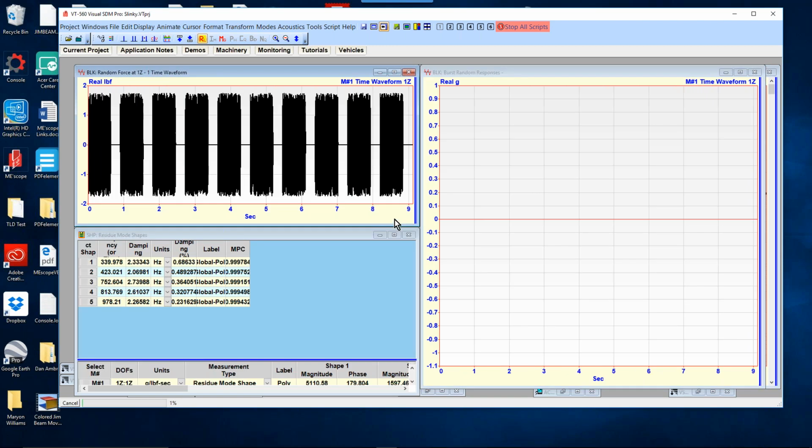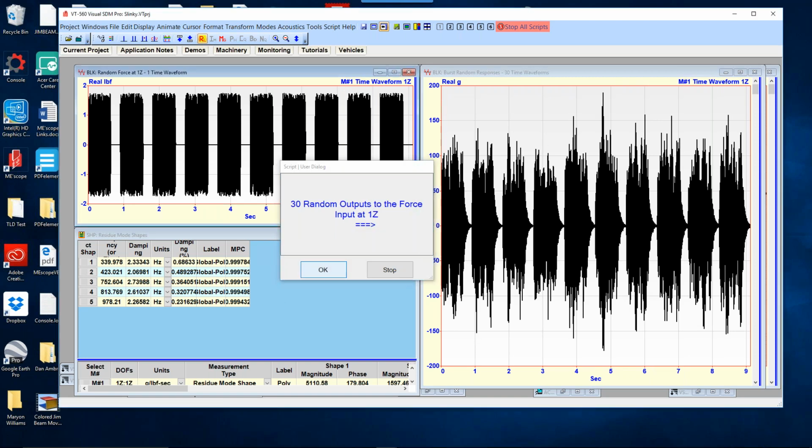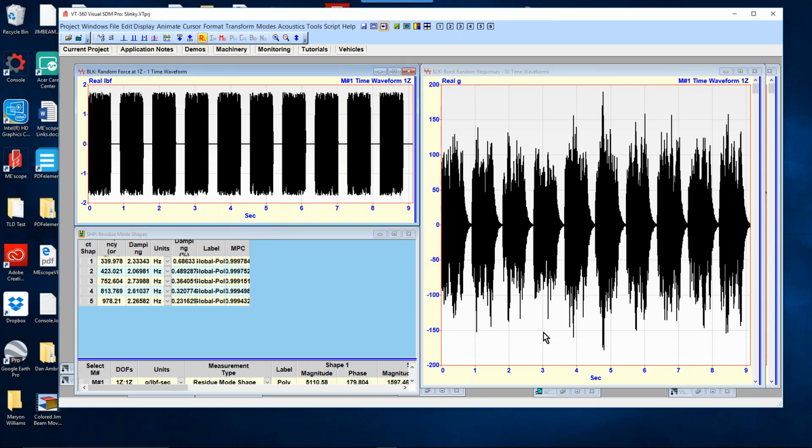Yes. That is seconds. Down here we've got seconds in this empty data block. If I go ahead and press this continue button down here, you can see that we get time records. So, yeah, I don't know how that got in there. That's a bug, but we corrected it by just doing the FFT and the inverse FFT. Good. Well, somebody was paying attention.